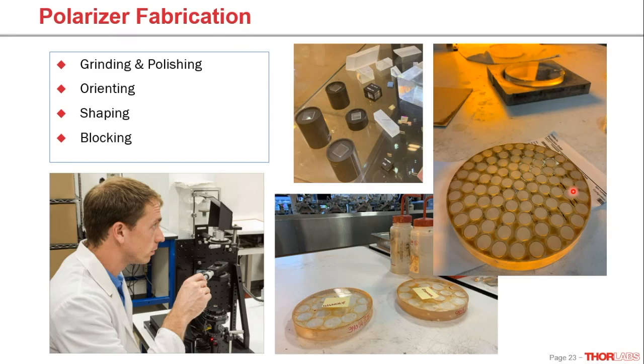So this is all balanced out at the same time with trying to achieve a high optical finish to that surface. In addition to this, it's also important that we select the right materials for the job. So in the cases of many of the polarizers, we see that calcite is often employed. A reason for the calcite to typically be utilized in these cases is because of the larger difference in the index based on the ordinary and extraordinary ray, or at least what they would observe.